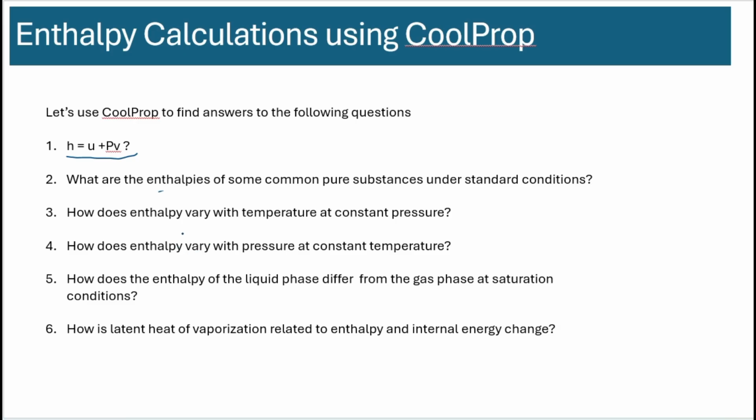Just like internal energy, we will check the effect of temperature and pressure on enthalpy. We'll also look at the claim we just made about the differences between the liquid phase and gas phase enthalpy at saturation conditions, and do the same for internal energy. Then we'll calculate the latent heat of vaporization using the enthalpy difference, and see what the internal energy change is during that process.